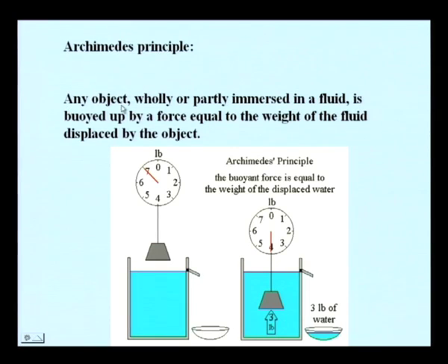That volume will be equal to the volume of the liquid displaced, and in addition, if rho is the density of that medium, rho into that volume will give you the weight of the liquid displaced, and that is the amount of weight that is displaced. That is what this figure tells. Any object wholly or partly immersed in a fluid is buoyed up by a force equal to the weight of the fluid displaced by the object.